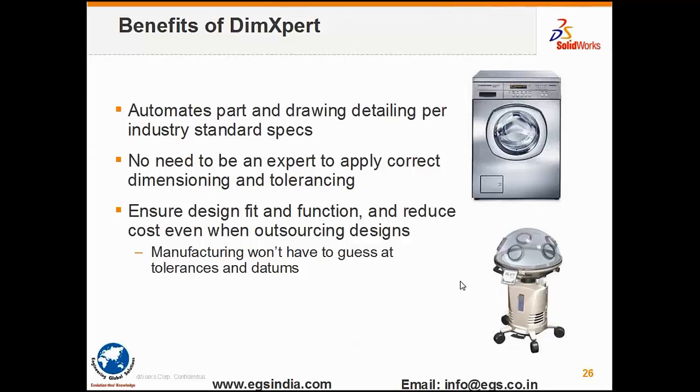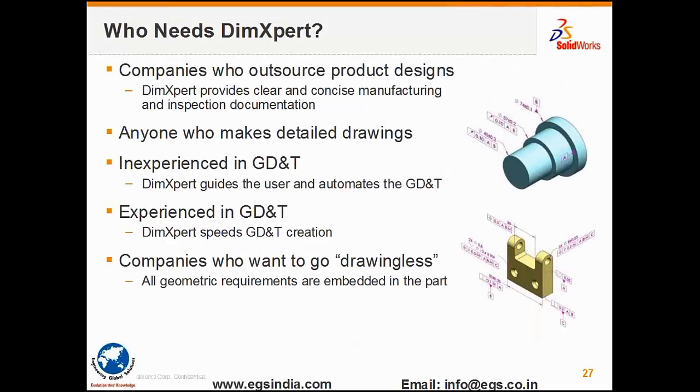There is no need to be an expert to apply the correct dimensioning and tolerancing schema. If you apply a datum for flatness, it will come back and say no datum is allowable for flatness. So to that extent, the syntax is brought in. That's why we refer to it as the syntax and the grammar. It ensures design fit and function and a reduction in cost even when outsourcing of design happens. Manufacturing would not have to guess at the tolerances and the datums because it is unambiguously put on the drawing.